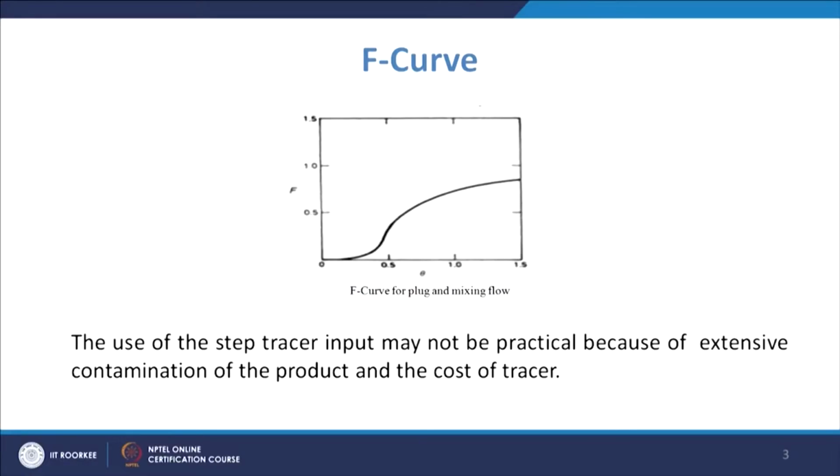But you do not prefer that, because if the tracer is going continuously into the molten steel, that may even contaminate the steel. You may like to have the concentration analysis at the exit, but that will certainly contaminate the whole steel. So, that is one issue.